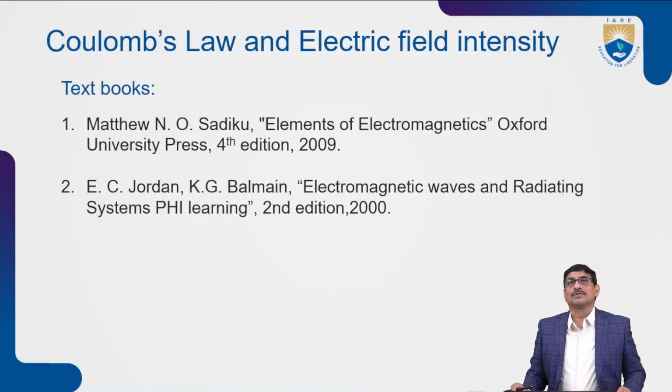Before we conclude, to summarize, we learned in the class how the Smith chart is obtained from the reflection coefficient equation. We considered the reflection coefficient equation and took the normalized terminating impedance, where the reflection coefficient and the normalized terminating impedance are both complex constants.